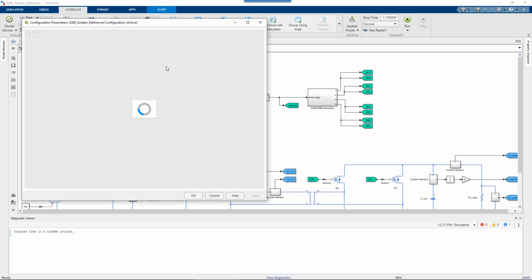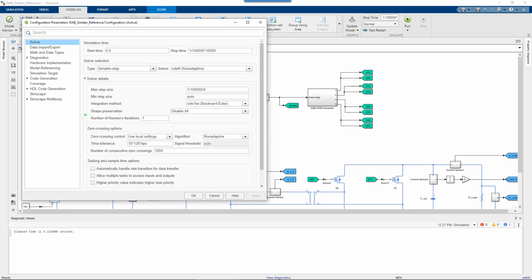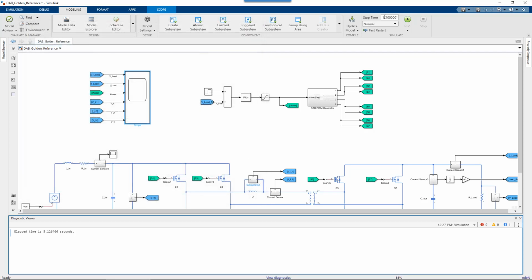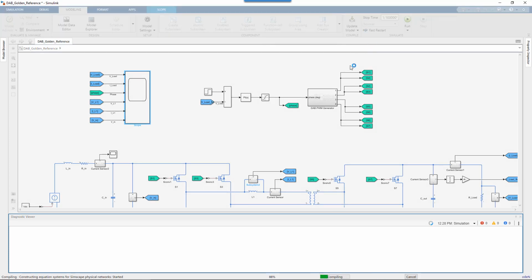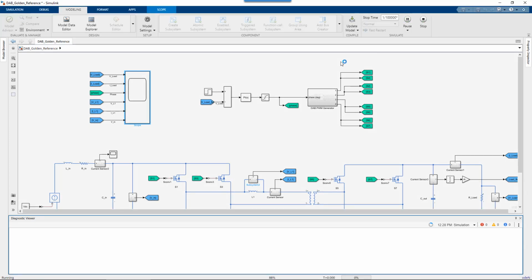One other thing you sometimes need to think about is the number of Newton iterations. Now, I can tell you since my model is accurate with ODE45, I probably don't need many more Newton iterations. This becomes more relevant basically the more you're actually using the Simscape solver, its capabilities. But 3 to 5 is, for complex systems, a more likely place. So sometimes you turn up the Newton iterations and that will improve your accuracy without changing your time step. But it's also going to slow things down.